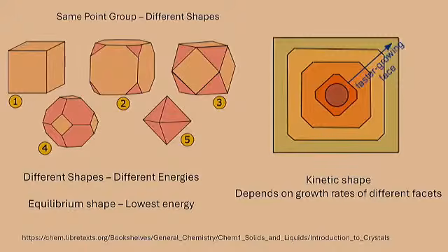The first one, what I call the equilibrium shape of the crystal. The equilibrium shape of the crystal is the one that has the least energy. Okay. If you sum up all the surfaces that have excess energy, if you sum up all the energies of these facets that are there, the equilibrium shape in this particular case for FCC is something like this: the cube octahedral shape comprising the 1, 0, 0 and the 1, 1, 1 facets. Okay. But in reality, when we actually see the crystal after it has grown fully, we rarely ever see the equilibrium shape.